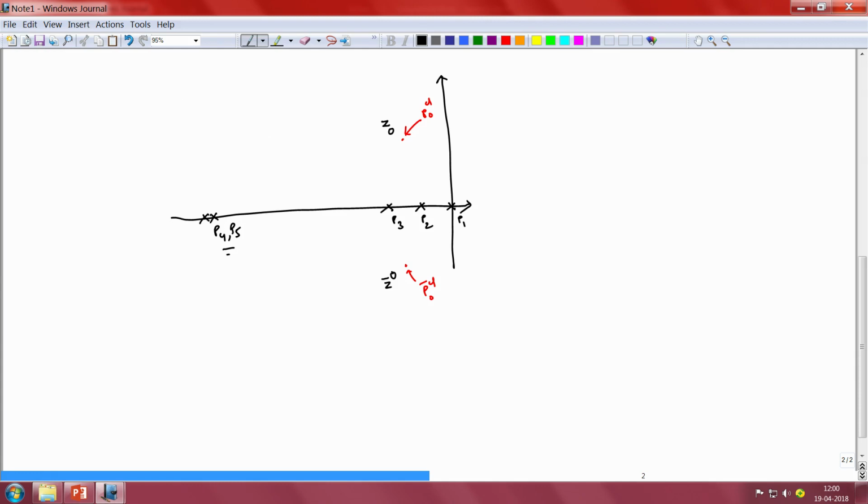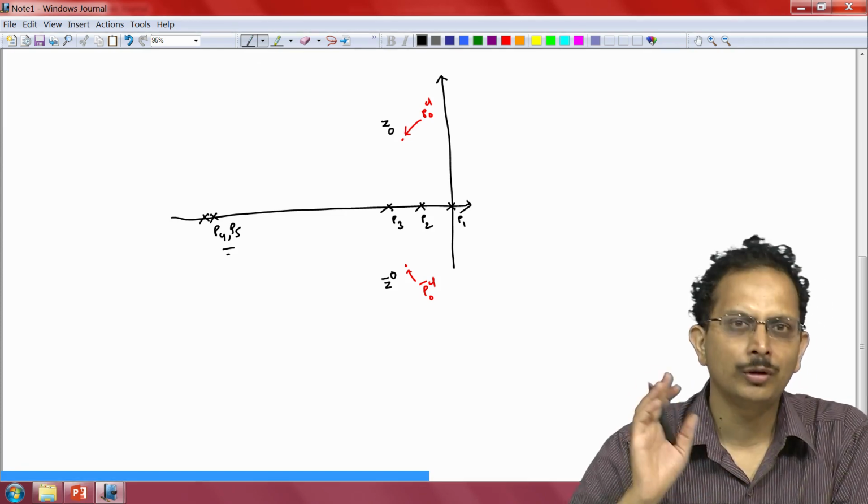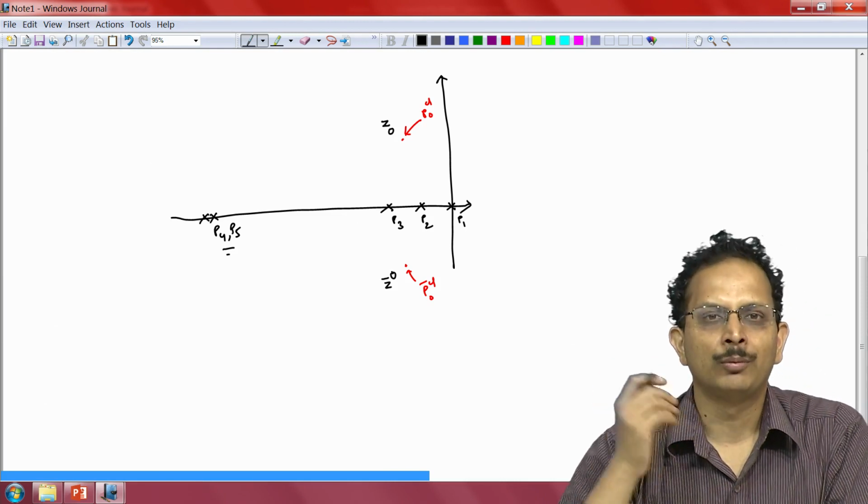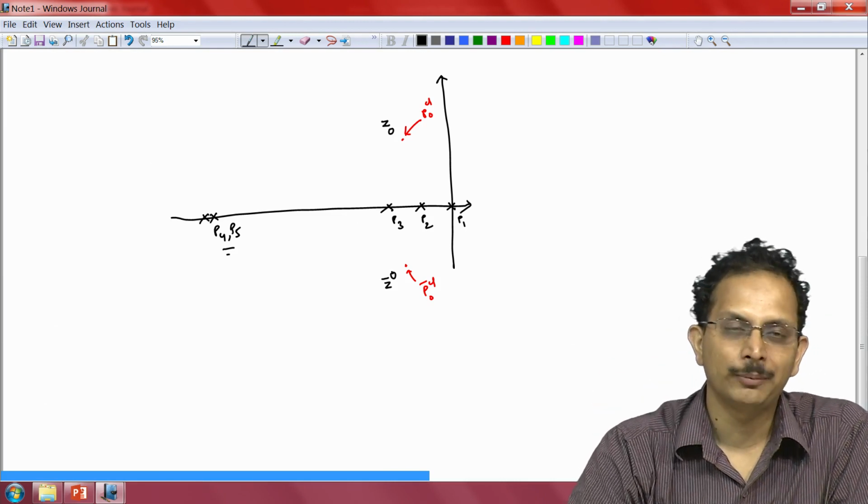The third step is to complete the feedback controller design, and that is to determine the gain of the feedback controller. So, the first two steps will allow us to determine the structure of this controller. It would have two zeros z and z bar, the specific positions of these zeros would be identified, it would have two poles. Assuming that these poles are coincident, then we would have the locations of these poles determined in the second step.